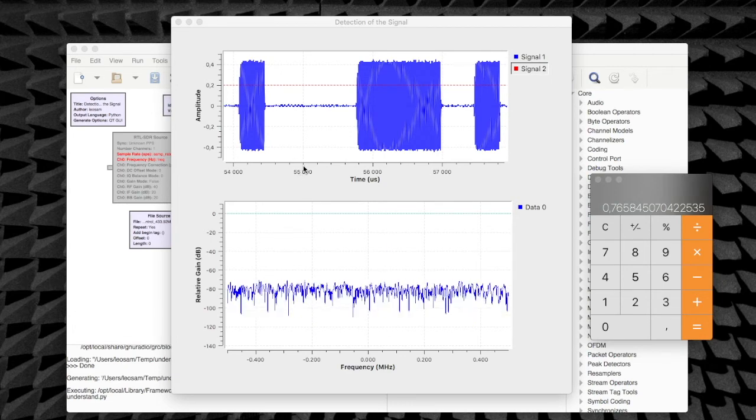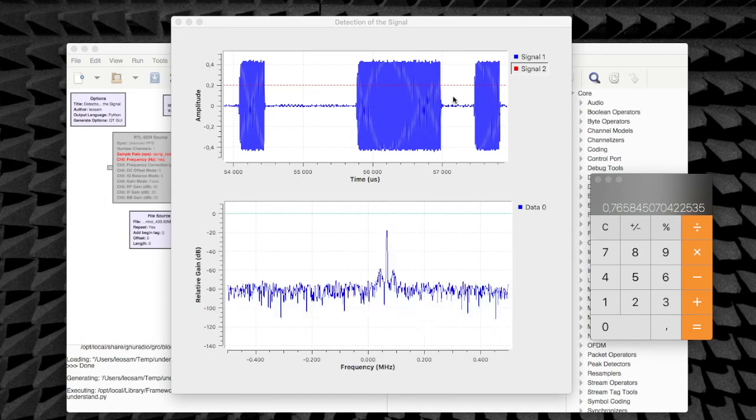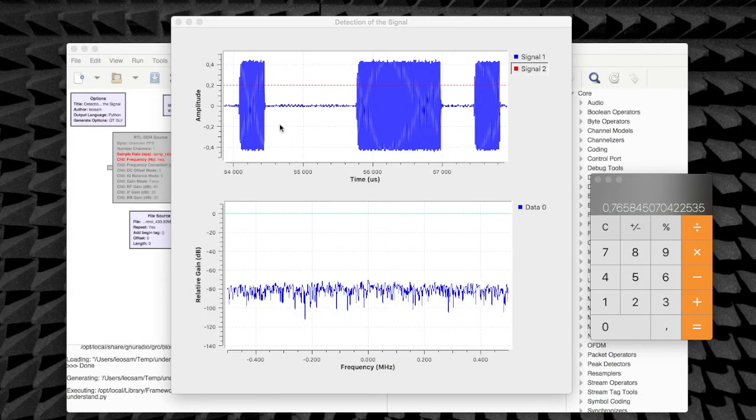In this case, what should we decide? Is the 25-75 a 0 or a 1? And in this case, the 75-25 will be the inverse of that. So should we decide this is a 0 or should we decide that this is a 1? Remembering that when we decide what bit this is, then the rest of it will be the inverse. And then we'll decide what is the full sequence of bits that we have here, and then we can start demodulating and decoding this signal.